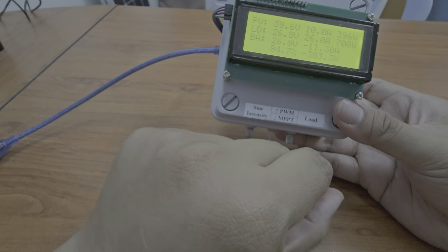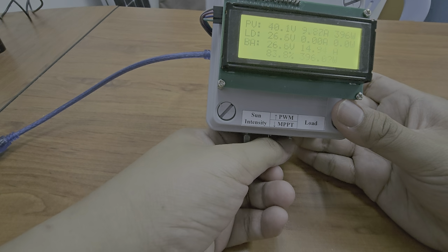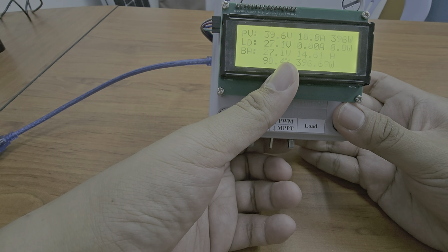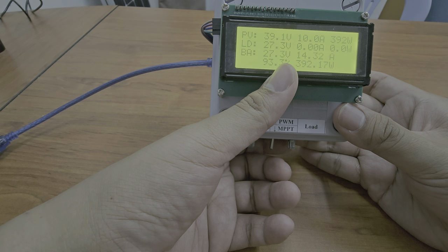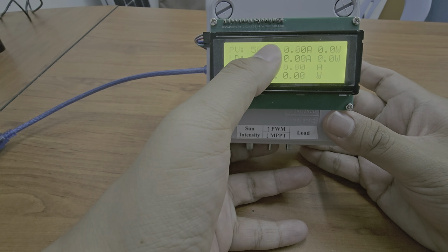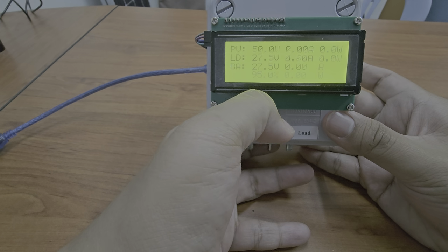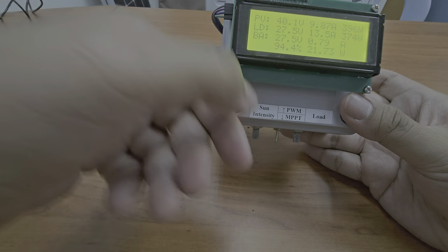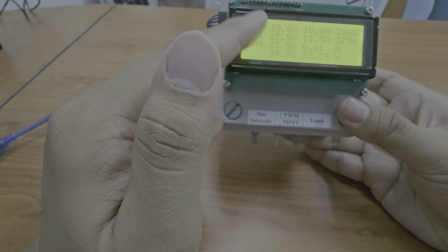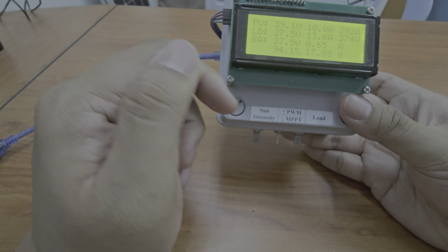So something like that. What happens if the battery is full? I reduce the load, and the battery will increase up to 95, same as before. It will disconnect. Basically the battery voltage will become very high and the current becomes 0. If I increase the load, it will be oscillating around that area. You can see this is oscillating, and it's called a floating voltage.